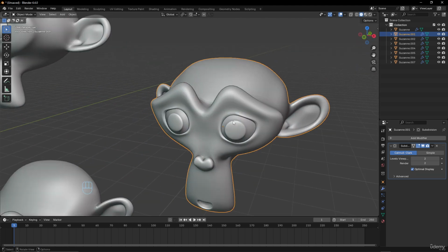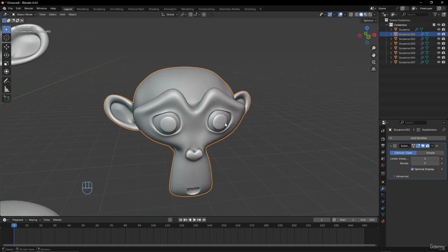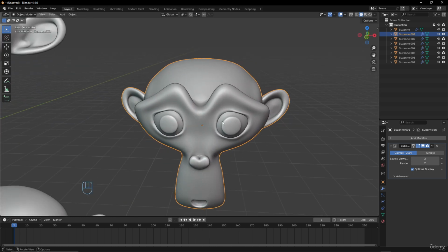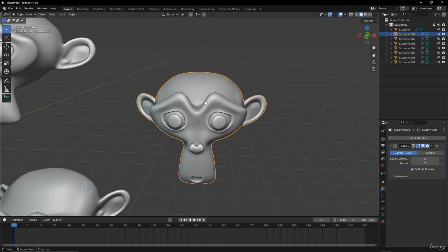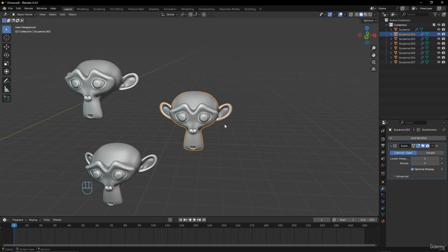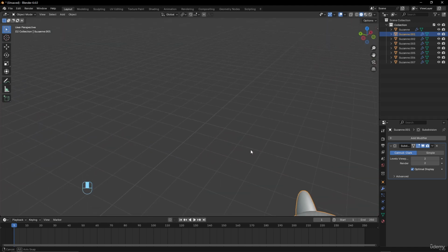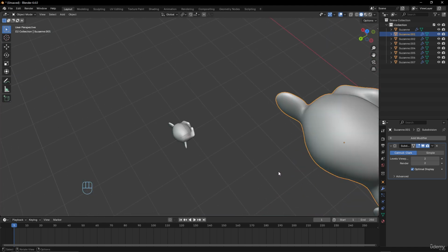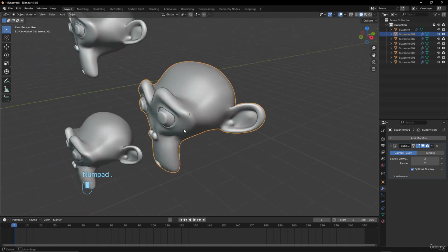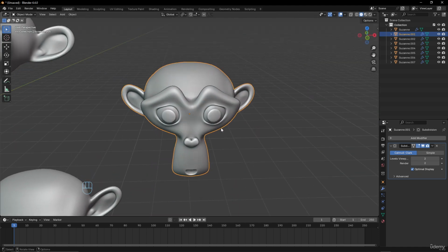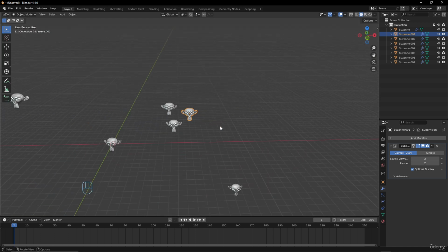So when you want to go somewhere in your file and focus around this point, make your selection well and use this dot under the 3 on the numpad. It's the most important to navigate well. And like this, you will save a lot of time turning around your object with shift and managing it like that and saying, oh, I'm not here. Oh, where is it? Oh, yeah, no, you just use that and it will work directly. Okay. So a very important one for the navigation and to navigate well in Blender.